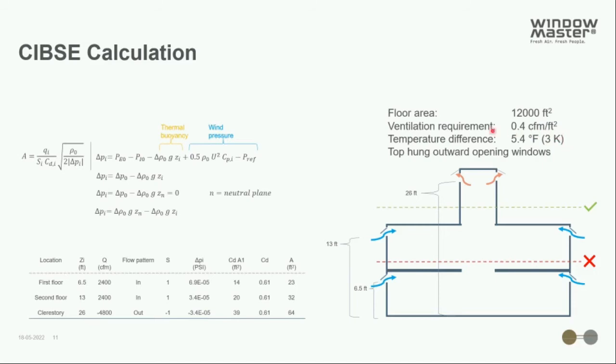And as compared with the table before, you can see this is a somewhat larger temperature difference. And this is also specified in the CIBSE AM10 that 3 Kelvin is a reasonable temperature difference to design according to, because in the end we also need to consider thermal comfort. So I want to base this example on this temperature difference.